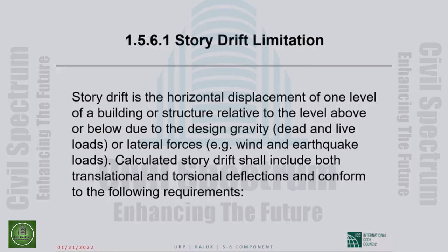So as I said, gravity loads seldom cause lateral deflections unless there is a distinct lack of symmetry. And in that case, you will keep dead plus 0.5 on your structure as you try to calculate deflection for wind loads. Calculated story drift shall include both translational and torsional deflections and conform to the following requirements.